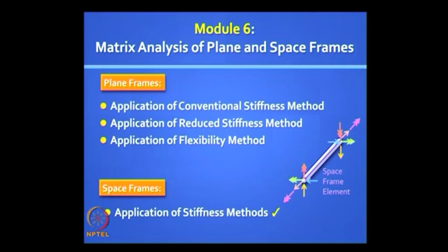The space frame element is an element which has the largest number of degrees of freedom. You have 6 degrees of freedom at each of the two ends, so you have totally 12 degrees of freedom,